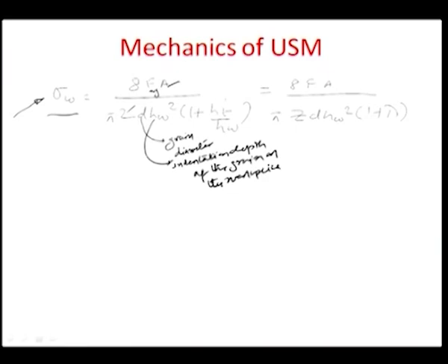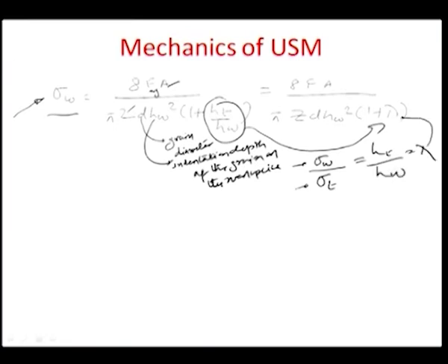and this parameter here known as lambda was basically the ratio of the ultimate flow stresses of the workpiece and the tool. As we have already seen in detail before, the ultimate yield stress is inversely proportional to the indentation depth. So we can assume that sigma W by sigma T, the ultimate yield stress of workpiece to the tool, is nothing but the inverse ratio of the depth of indentation of the tool to the workpiece, and this we considered as lambda here, which comes into this equation. And so we have ways and means to predict the ultimate yield stress of the work material here.